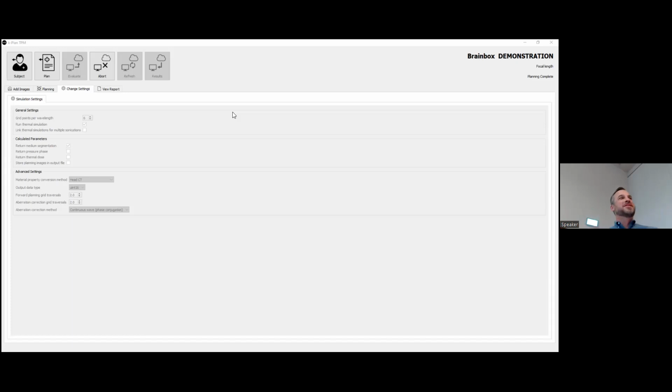The skull is a perfect acoustic matching layer, by the way, to PZT. It's the geometric mean, about 5.5 megarayls. So if you took off the skin and coupled directly to the skull, it may not be quarter wave, but you would actually use the skull as a matching layer. And you wouldn't have that reverberation in between.